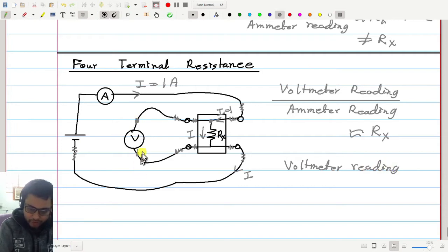However, that is also very close to the voltage difference between this point and this point, because the voltage difference from here to here has 3 components, one drop here, one drop here, and one drop here. But these are small drops compared to this drop, because voltmeter resistance is high compared to the junction resistance, which are negligible, I mean much smaller than this.